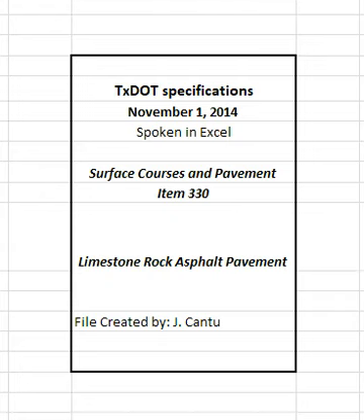Use a motor grader to spread the mixture when shown on the plans or as approved. Thoroughly aerate the mixture and spread into place with a power motor grader in a uniform layer. Placement in narrow strips or small irregular areas may require hand spreading.